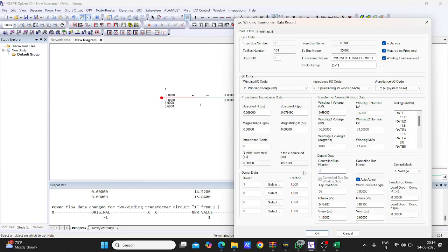Okay, I hope your point is clear. Now let us consider we have 17 taps. In this transformer data sheet, we do not have an OLTC. This particular transformer data sheet is a fixed tap. We do not have any OLTC for the particular transformer whose data I showed, because it's an inverter duty transformer. So this transformer does not have any OLTC.